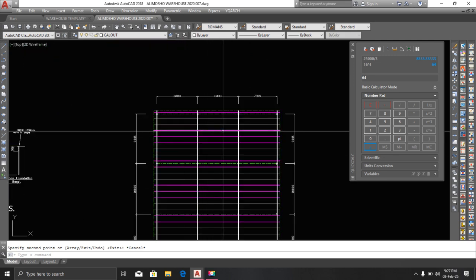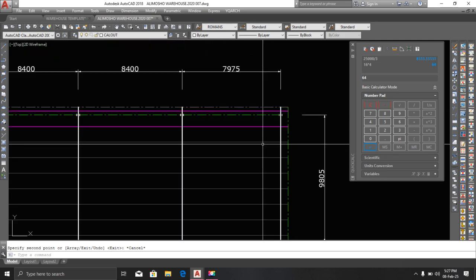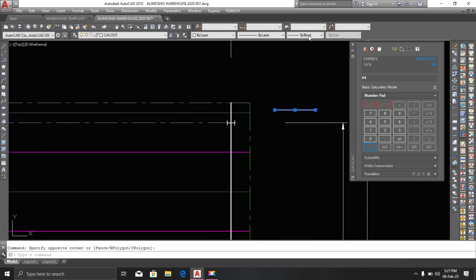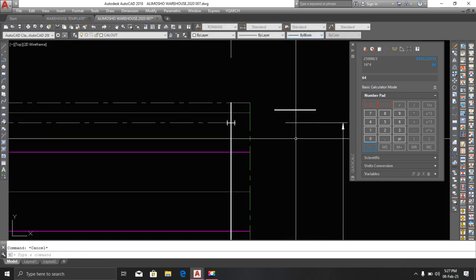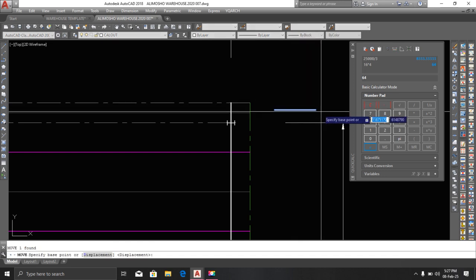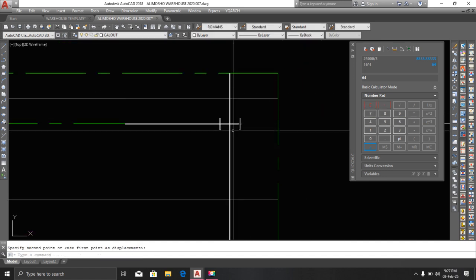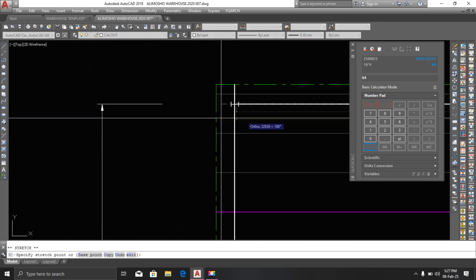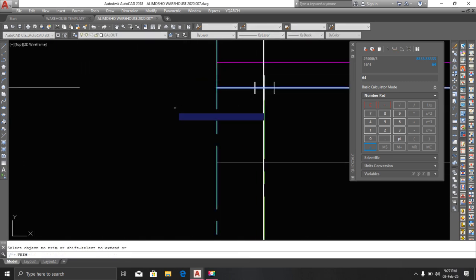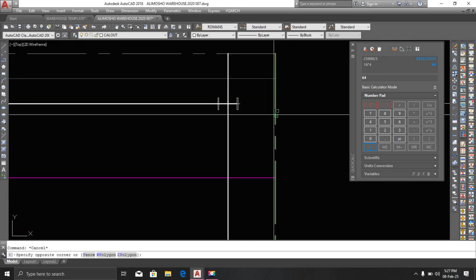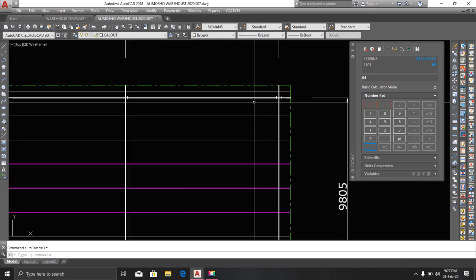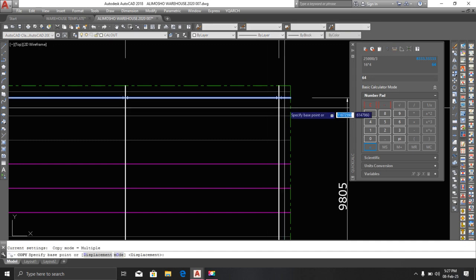So next step is let me have my tie beam. For a tie beam, I want to have something vertical. Click on it, change it to white 0.4. So click on this, bring it down. So this will be my tie beam. So click on this direction, come down here, drag it down here. So this just extend. Alright, I have something like this as a tie beam. Copy it also.